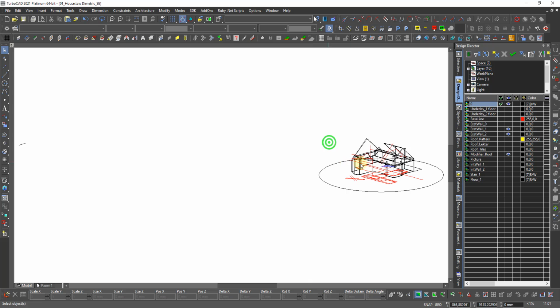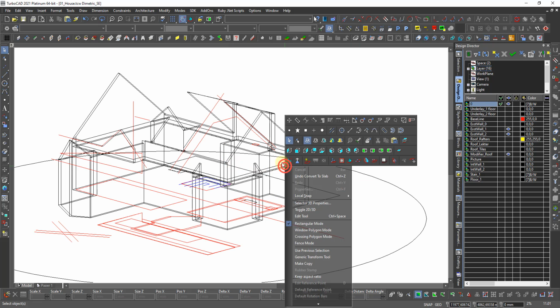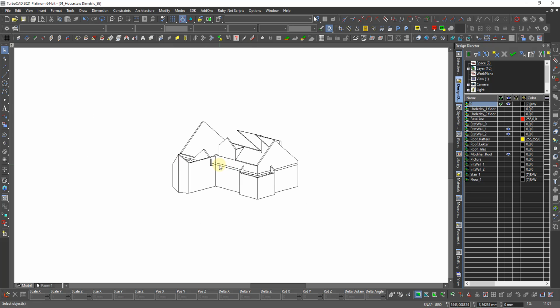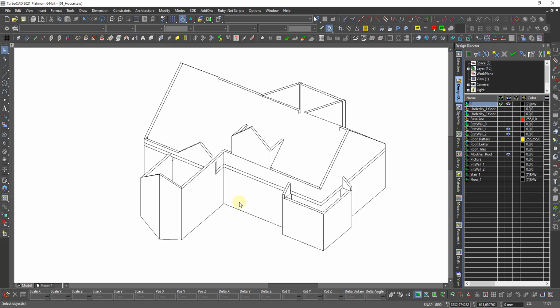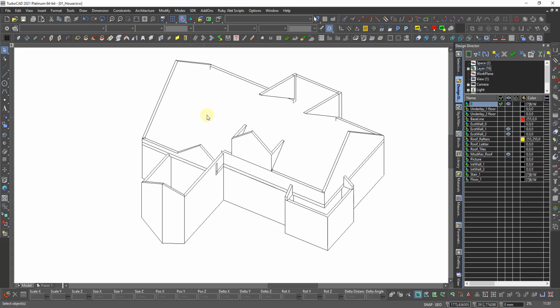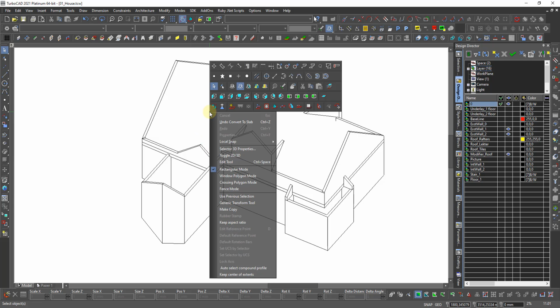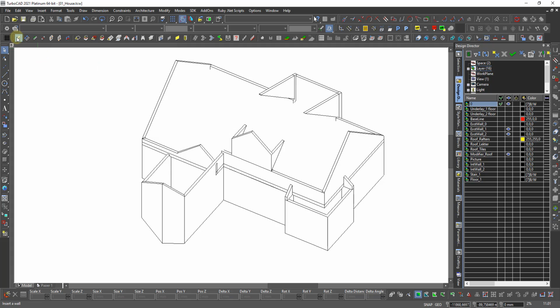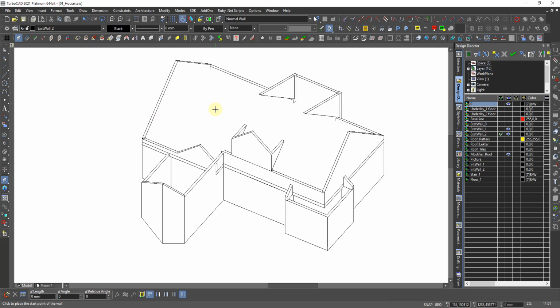Open perspective, I say hidden line, and now you see this coming in as one big slab instead of many small. Then I can set the work plane on top. I face it on that floor. And then I can draw some wall. I have it linked.